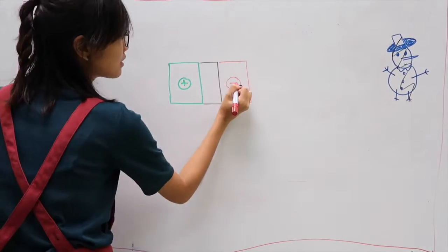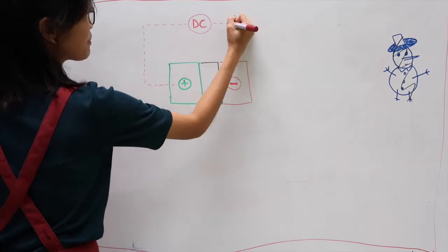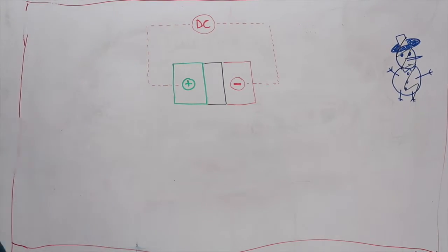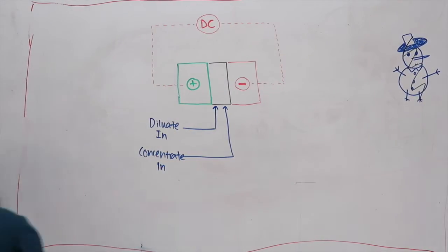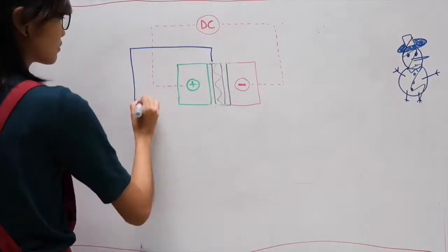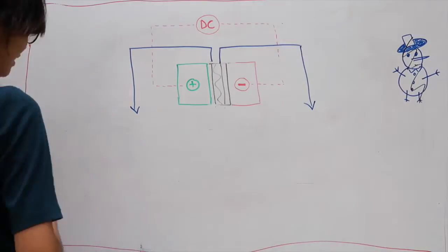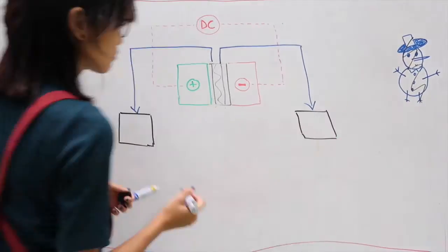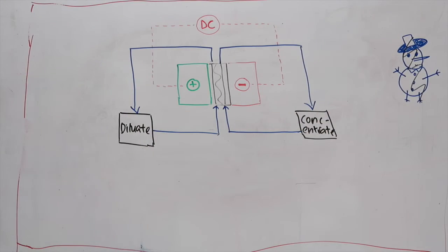There are two processes that can be used in electrodialysis. Firstly, there's the batch process, the simpler of the two. Here, the solution is circulated in the system through the stack until it reaches target conductivity. This leads to high energy consumption. The concentrate stream is partially recycled to reduce wastewater volume and is injected with acid to prevent scaling.